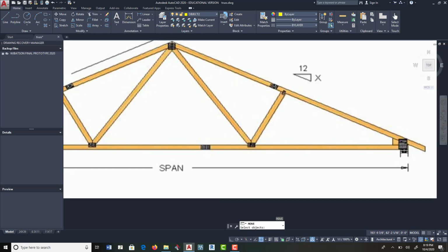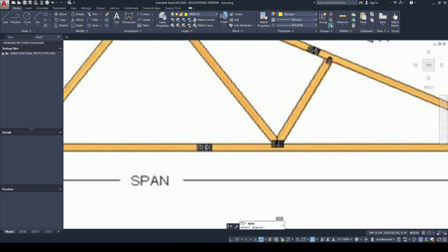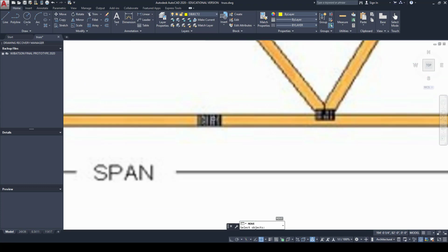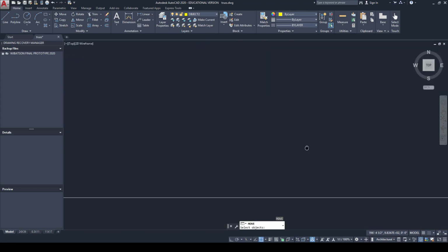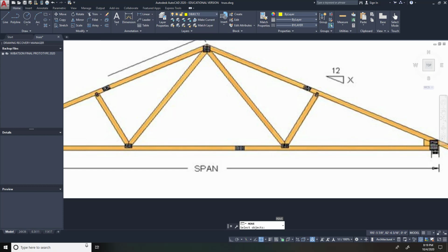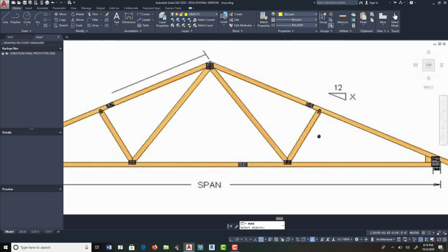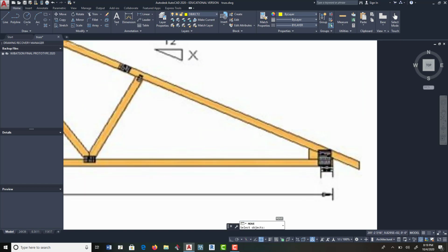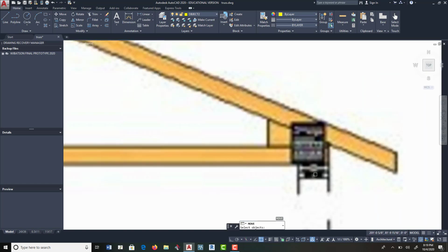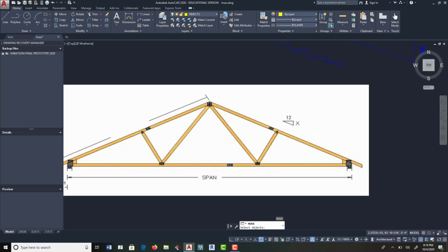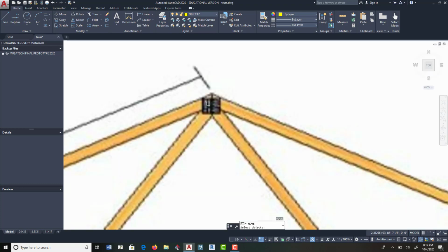These are truss plates right here. This one is because very seldom do you find a piece of wood that's 24 feet long. So you get 2 pieces and you splice them together and you nail them with this truss plate. And this is how these trusses are connected. And these are 2 pieces, and you're going to have to draw that line between there, and they're bolted there. The corner is bolted. There's 2 2x4s for the top plate where the truss rests. And then this one, if this is 2 pieces of wood, it's a plate right there. And at the top, there'll be a plate.